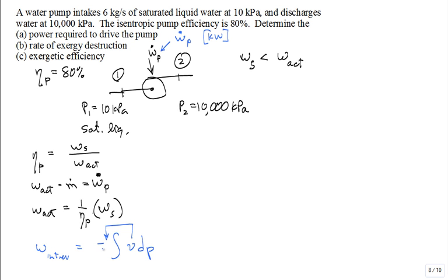Compressed liquid. It's liquid, liquid, liquid going through the pump, right? Is it going to be compressed, or is V constant? The specific volume is constant for liquids. That's our big assumption. It's well justified. So then that comes outside, and you just have minus V dP, so P2 minus P1. If you have a pressure increase, the outlet pressure is higher than the inlet pressure, then that sign takes care of it because we know we have to supply energy in the form of work to the pump.